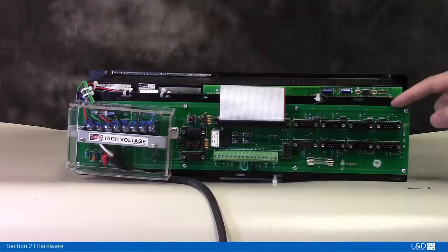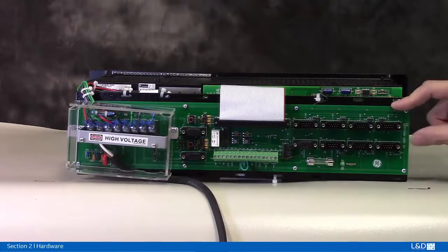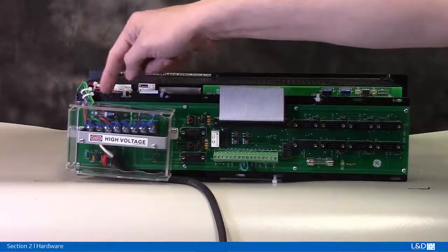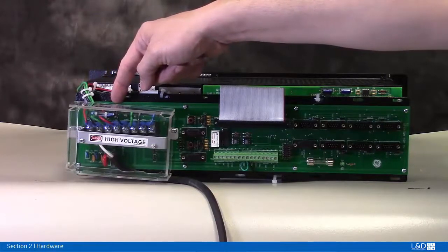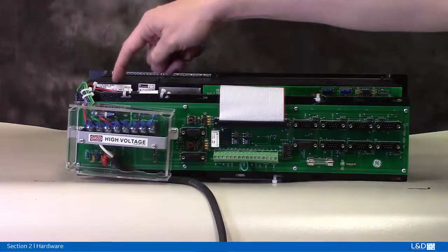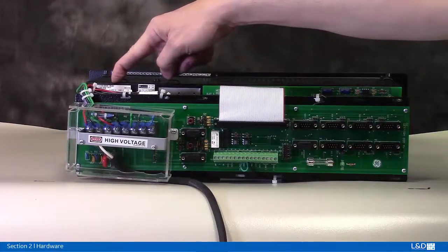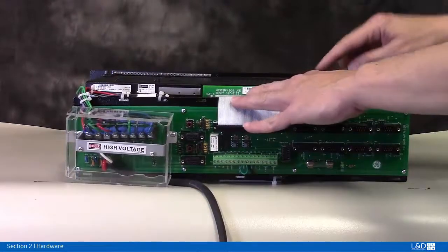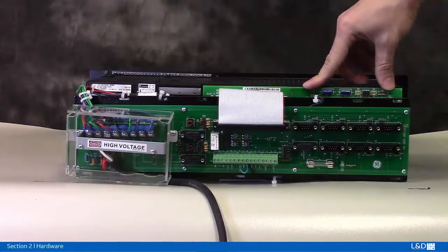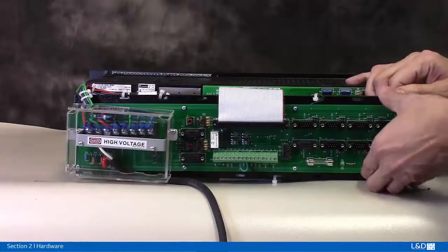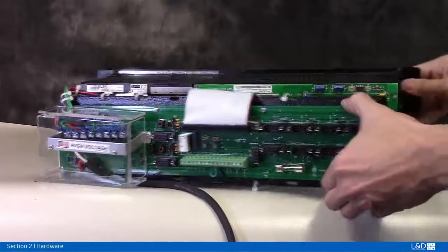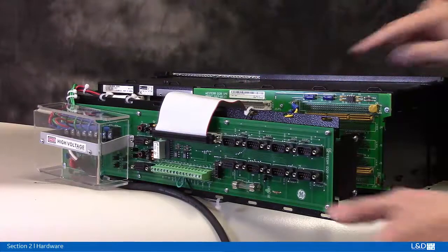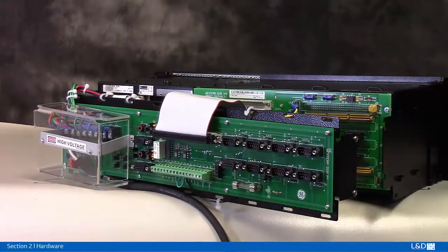The important thing is to remember to locate your serial numbers. On the D20 MX board, you will find the serial number under the power supply glass cover, okay? And then the main chassis will have a serial number on it. And then you have a serial number for the Westermo VME card on the back of the D20. If I open it up a little just to show you, this is your Westermo VME card, okay? And so that's your D20